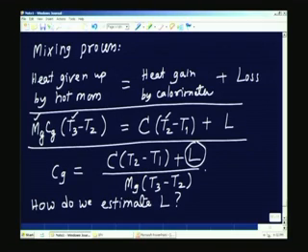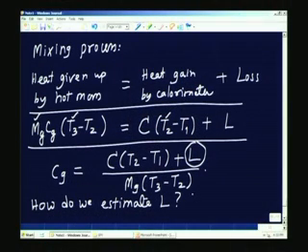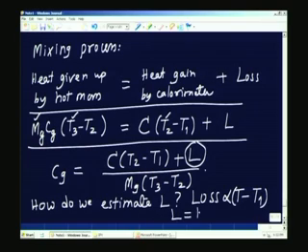We can make a suitable assumption for this. If you remember in the radial flow heat conduction apparatus, we saw that the loss is proportional to delta T, the temperature difference between the inner cylinder and the outer cylinder. Therefore, I can assume here also that the loss is proportional to the temperature of the calorimeter minus the jacket temperature T1. Actually, I can say that loss equals some K multiplied by (T minus T1), and if I know the value of K, I will be able to determine the loss, and then determine the specific heat accurately.